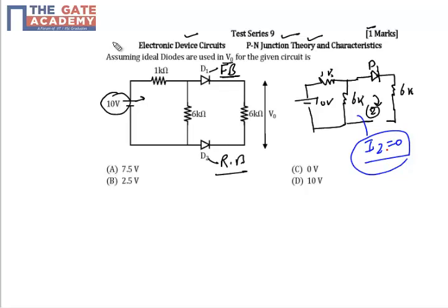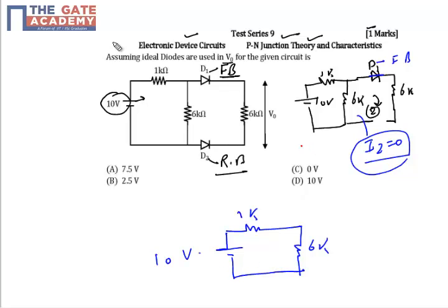then the diode D1 also cannot act as a forward bias. It can also not act as a short circuit because there is no current across it. So effectively you will have a circuit like this, because no current is flowing. A diode is a passive device. It will only act as forward bias in the forward bias condition, because no current is flowing here, there is no closed loop. So diode D1 is not going to act as a forward bias. So effectively the circuit will act as a no connection.